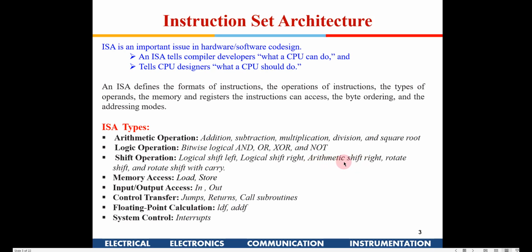Arithmetic shift left doesn't make any sense, because it will always be 0 which is inserted. You can't insert 1, because that will change the value of the number itself. So there is no meaning of having an arithmetic shift left. It is always logical shift left, whereas logical shift right and arithmetic shift right are different.